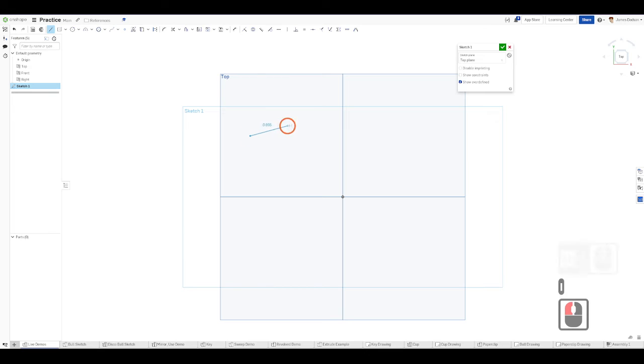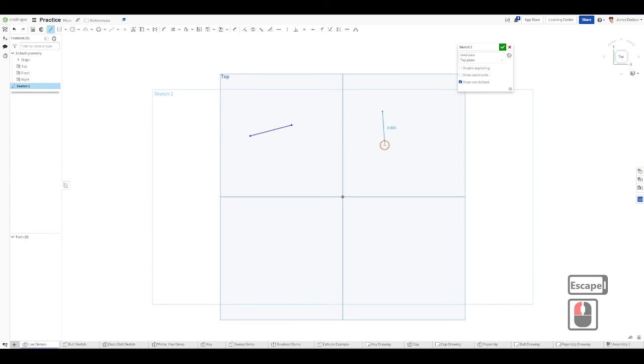First of all, I've got two lines. I want this one horizontal. Press H or select the horizontal button from up here. I don't even know where it is. This one here. It looks like a horizontal line. We can make this one vertical. And now they're constrained to be vertical. They can't ever change angle. This one's constrained to be vertical. This one's constrained to be horizontal.